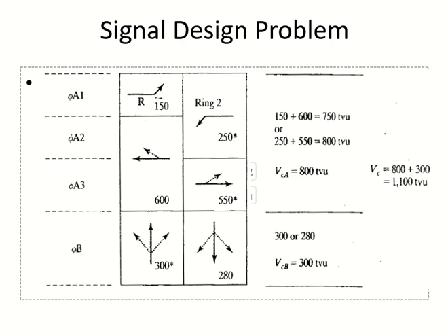I'm looking at my signal and the signal is green. I need time, right? Somebody has to honk at me and tell me to go. Got it? So there are minimum times for this as well. We are not covering this, but if the time is so less, for example, I don't remember, maybe the minimum time for green is 10 seconds. So what will happen? This 8.4 will become 10, and this 4.8 will also become 10.